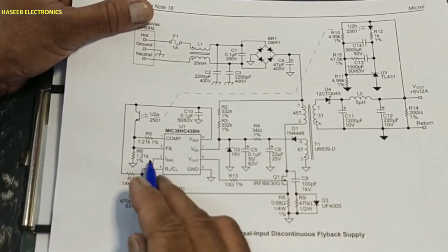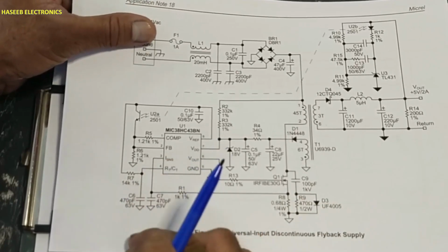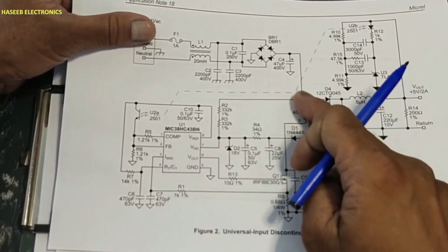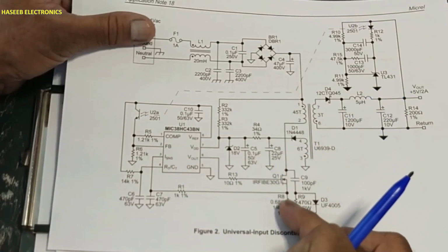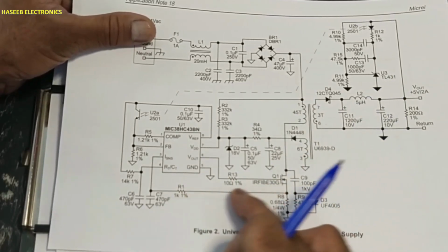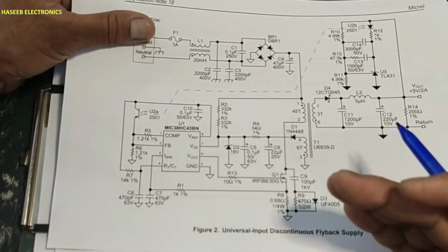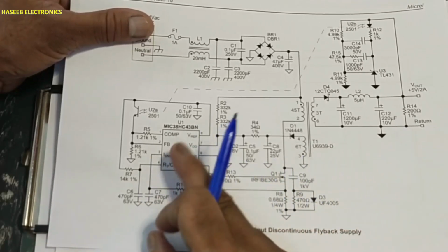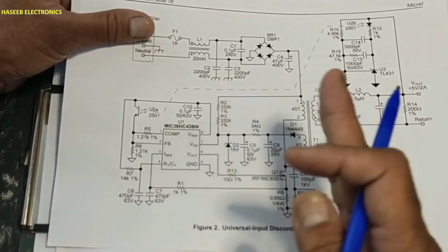That will cause false switching for this IC. The circuit is drawing just only 0.5 ampere, but its feedback network, current sense circuit, is not working properly. It is providing false output to trigger this IC into leading edge blanking.